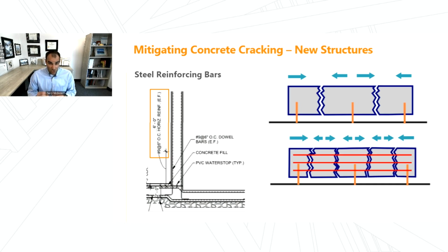The other way you can do that, as we talked about the reinforcing helping to dictate where our cracks and how active our joints might be, is we can add more reinforcing into areas where we know we have a lot of restraint. Now, additional reinforcing across a potential crack plane doesn't eliminate the shrinkage and it doesn't eliminate cracking. What it does is it distributes the cracks out over a couple of cracks instead of maybe just one wide one. So that's the figure on the right here.